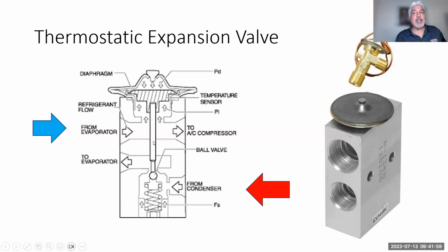Now I got to tell you though, sadly, there's a lot of cheap air conditioning parts sold out there, because I have put on these blocks from the local auto parts, Joe Blow name brand, and guess what? It's not regulating properly. I definitely did not see the change like I see where we're going up and down. So I had a deficient, or rather crappy, expansion valve, so I had to go with another one. So please note, not all expansion valves are the best quality in the world. Definitely pay attention to that.